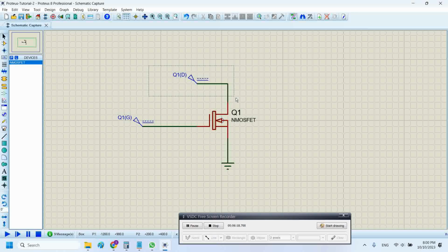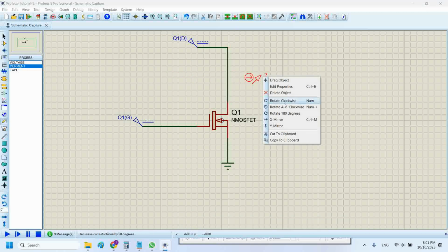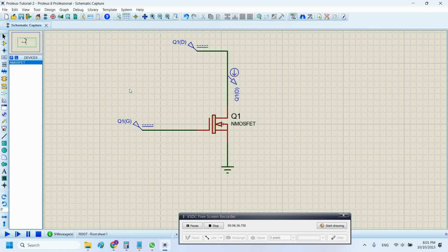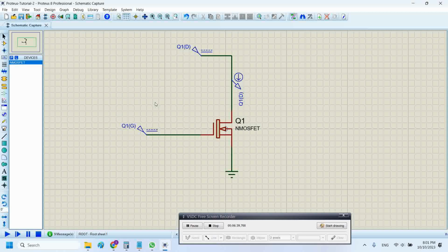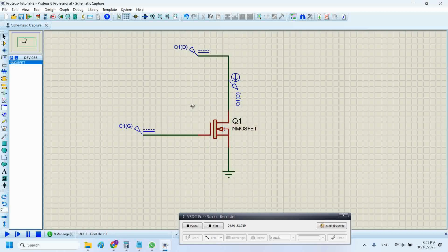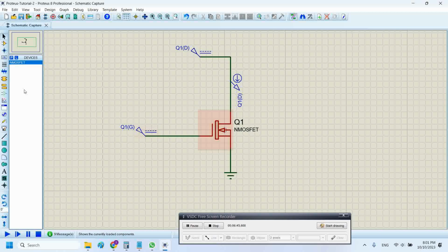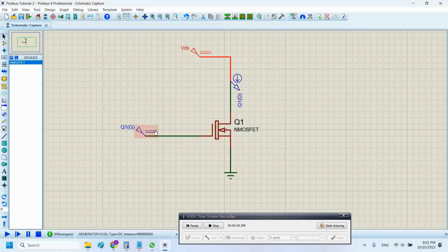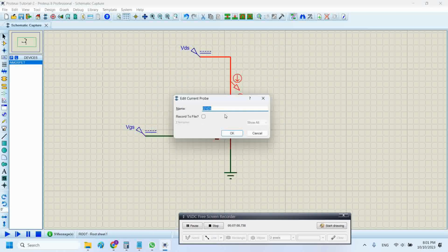As you people know that the DC characteristic curve is for the current probes, because it shows the relationship of the drain current to the drain to source voltage at applied particular gate to source voltages. So N MOSFET always works on the positive gate to source voltage. So I will simply leave this as it is and rename this as VDS, and I would rename this as VGS and rename this as IDS.